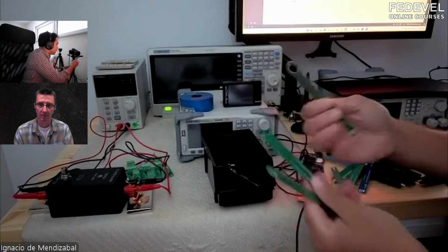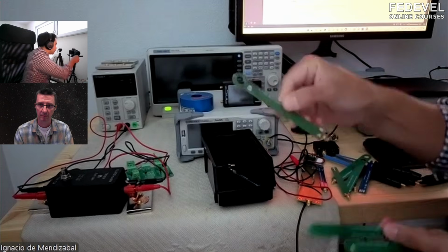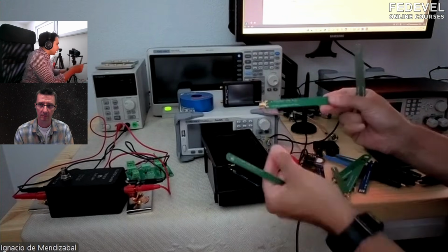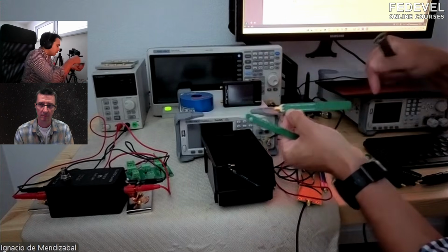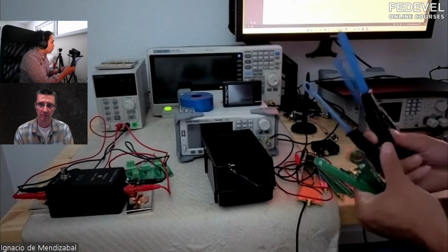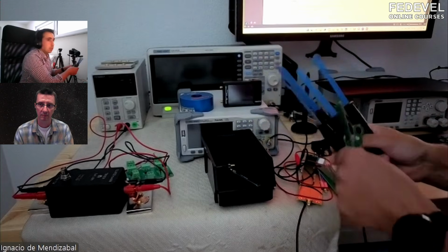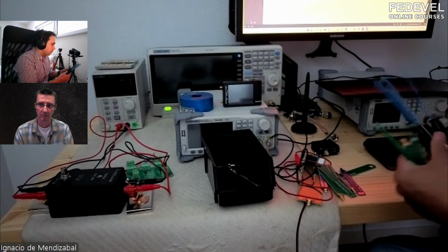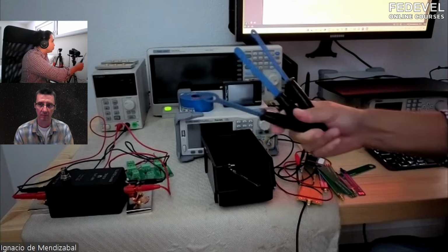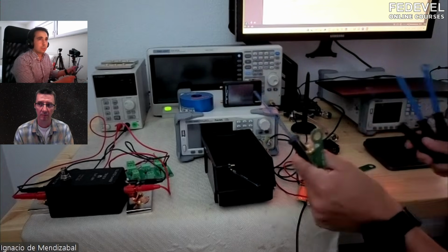And so this one with a loop, with a circle, is a magnetic probe, and then we also have another kind of probe, which is the electric one that has just a long trace. So those are PCBs, and we will compare them with some commercial ones. Those are from TechBox. You can buy a kit, and then you get four types of probes. In this case, they send you three magnetic ones, and also one electric.